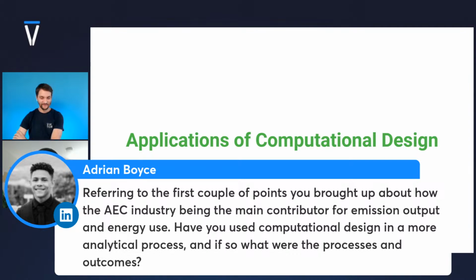Yes. Okay. So I was teaching computational design in Cape Town, and in Grasshopper there are a lot of tools that you can use for this sort of analysis. I know Grasshopper has LCA tools. For instance, the one I saw was Bombyx, which allows you to do a lot of LCA, lifecycle analysis, calculations. But a lot of the data used for that is European, so it wouldn't really work here. We will have to gather the material data needed for it in South Africa. I think Adrian is from South Africa.